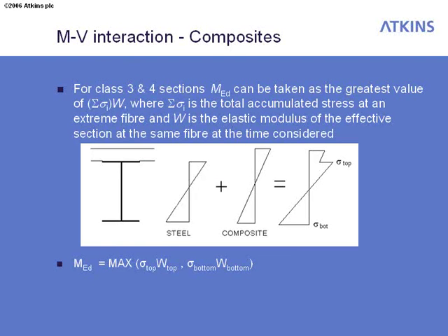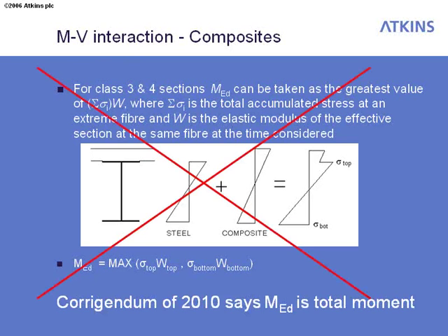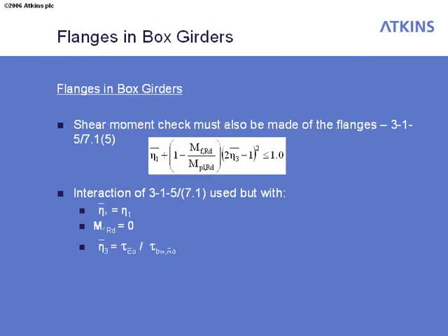Instead of modifying the moment in the way that's mentioned on this slide, you just use the full actual moment within the section. So again, just something to make sure you're aware of, and when you do come to that part of the Thomas Telford guide, write yourself a note to say this is no longer what we're doing, because the code's been modified since then.